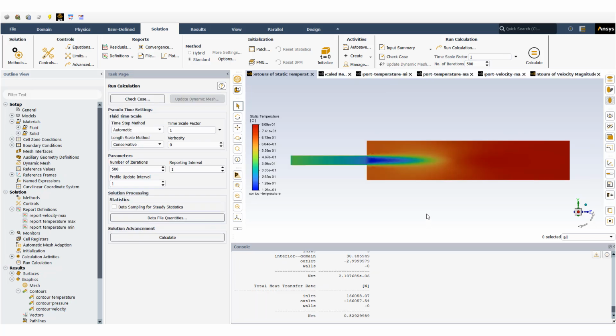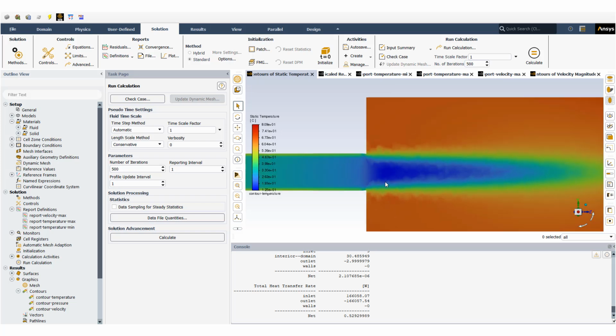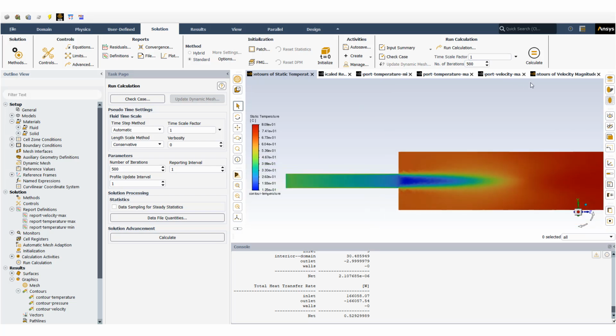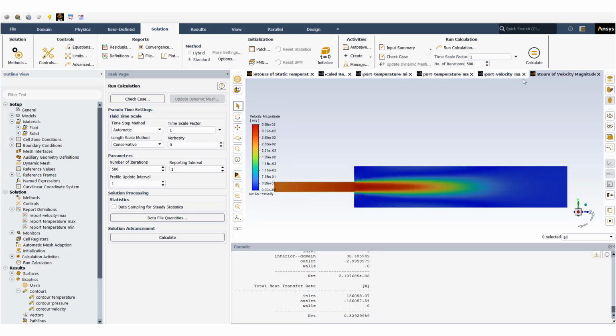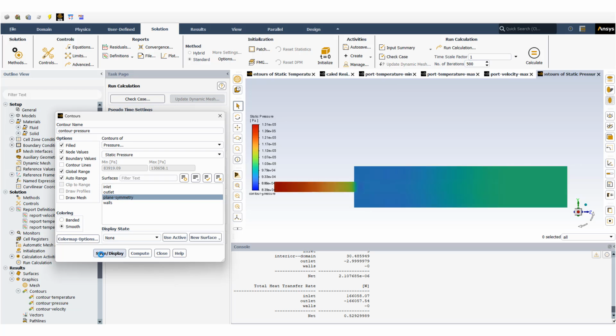So in this simple example with this opening, we could show that cooling happens due to sudden expansion in a closed system with no heat exchange with the environment, and this expansion of the volume causes the temperature to drop, the velocity to accelerate, and the pressure to drop.